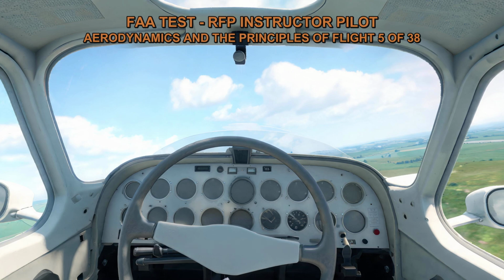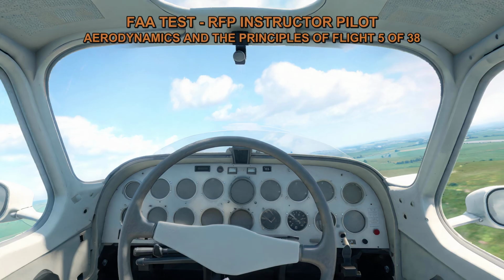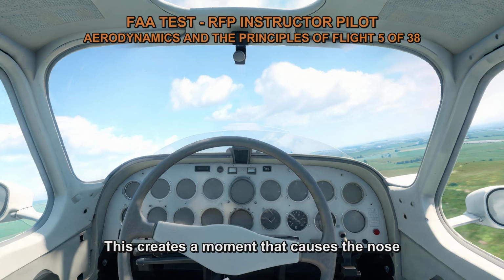rotate the airplane. The downward force of the weight acts through the CG, while the upward force of the thrust acts below the CG. This creates a moment that causes the nose of the airplane to pitch upward. In contrast, if the line of thrust were above the center of gravity, it would create a moment that tends to make the nose of the airplane pitch downward.